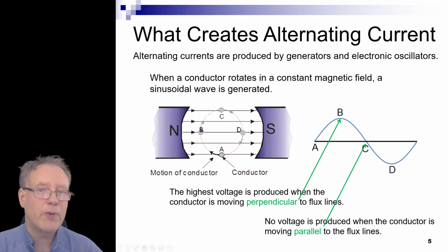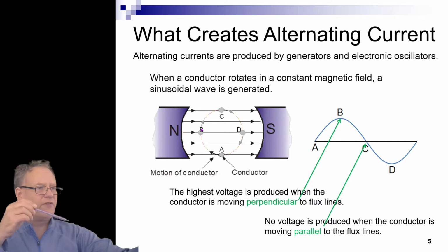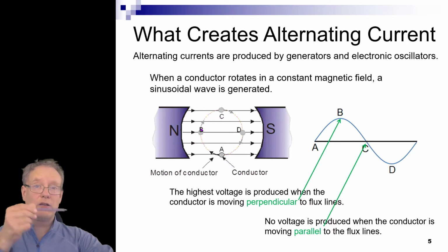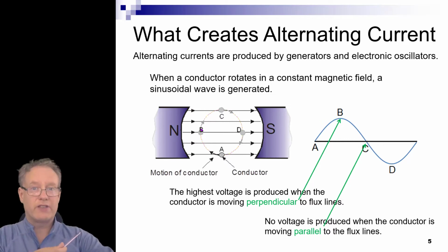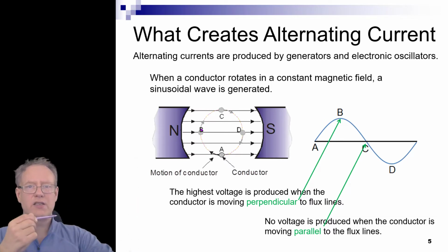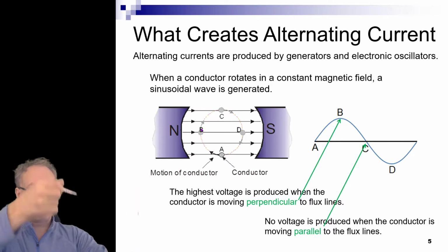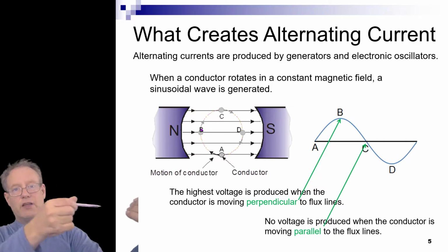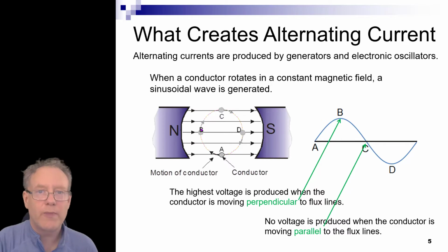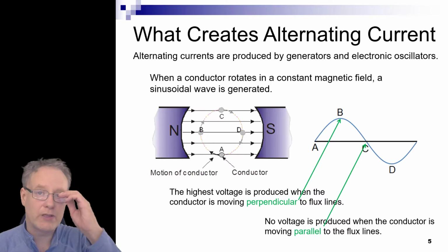So it starts to move perpendicular to the magnetic field. One of Faraday's discoveries was that if you put this conductor straight up and down at a right angle to the magnetic field, the actual EMF is at the greatest. But if you go through at an angle, as I'm doing this, it's greatest, and then it's a little bit less, a little bit less, and if I do this, it's nothing. So as our angle of attack changes through the magnetic field, we get less EMF. And that's why the sine wave happens as this thing's rotating.